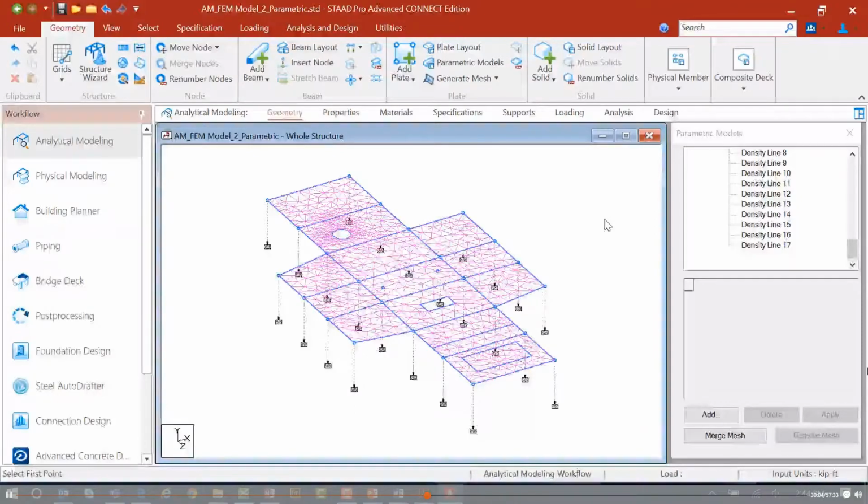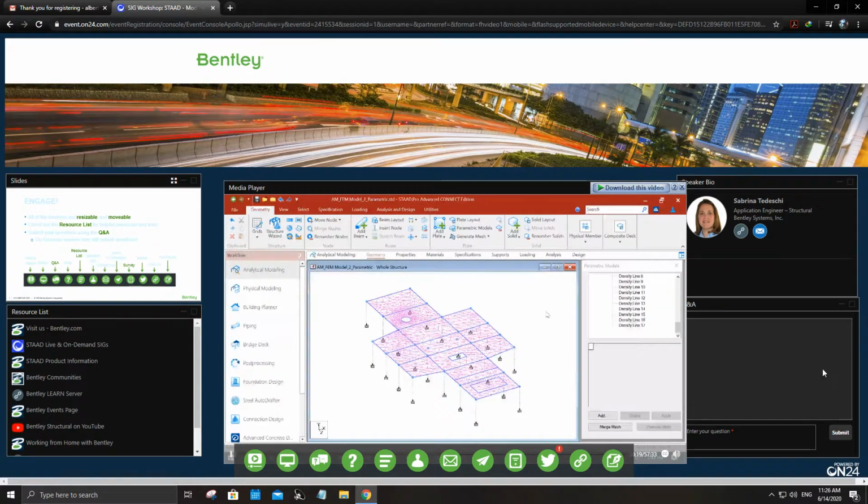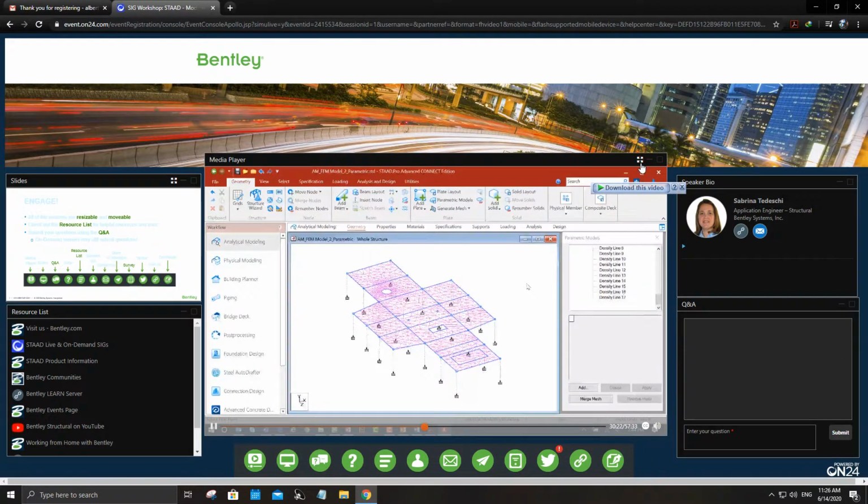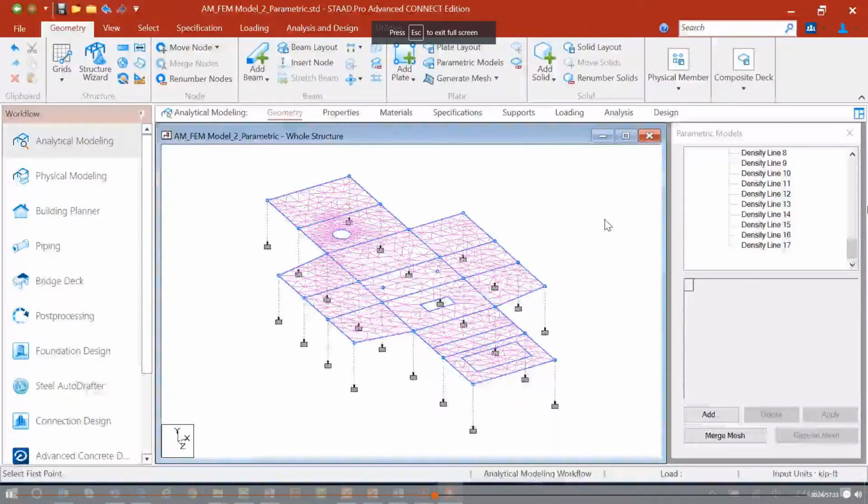And of course, that's probably your best workflow for designing concrete walls that were modeled in STAAD.Pro: create them as a finite element mesh, analyze them with that meshing system, and then transfer them over to the STAAD RCDC workflow. Now at this point, I've previewed and massaged my mesh the way I want it to, and I'm ready to commit it to my STAAD.Pro model. Again, I could have created more than one prototype if I wanted to, but I like this one the way it is. Once I'm ready to make that official move over,